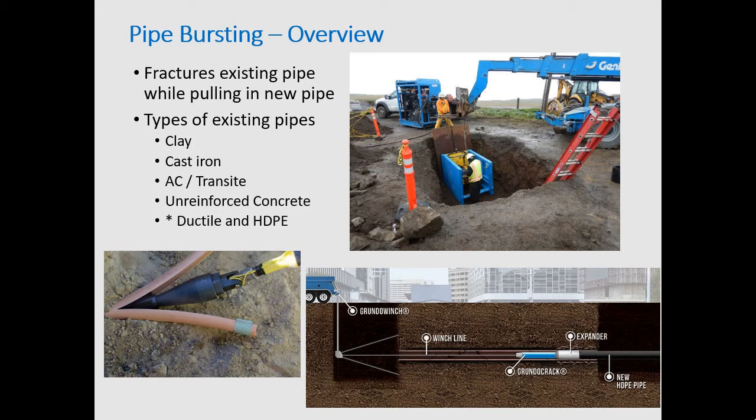So quickly, the pipe bursting overview. When you type pipe burst, a lot of times if you Google it, you find a burst water main, and you have geysers of water. Well, pipe bursting is a trenchless technology that replaces the existing pipe in place with a new product pipe. This is the one technology that actually increases your pipe capacity, and I'll get to that in a minute.